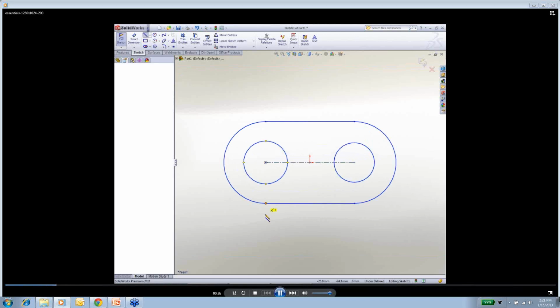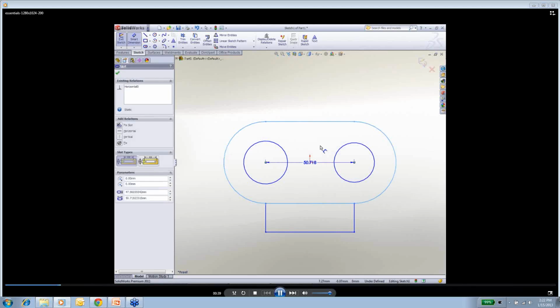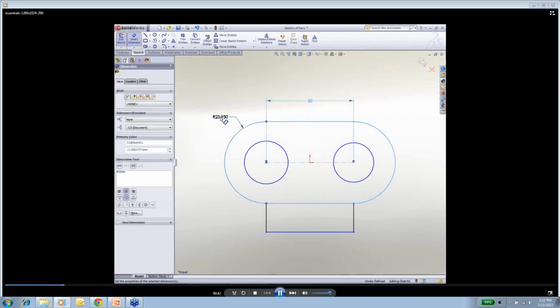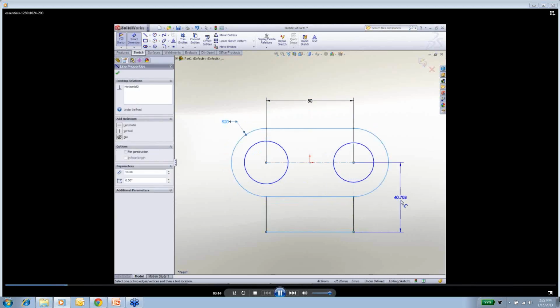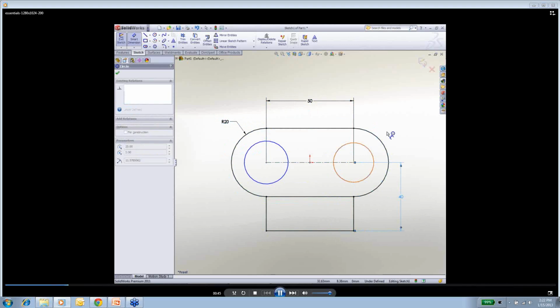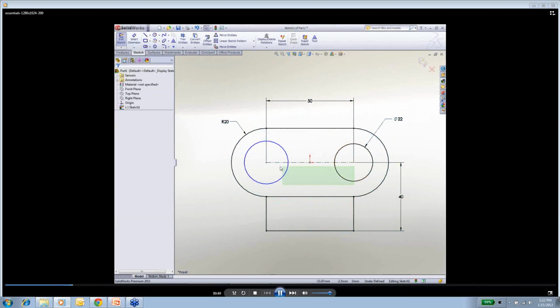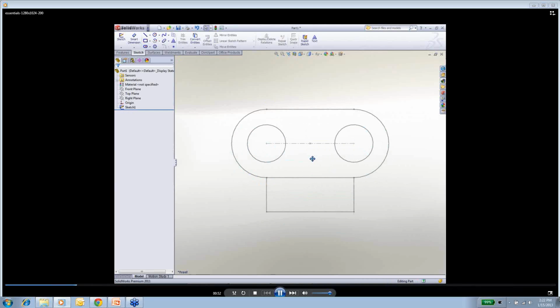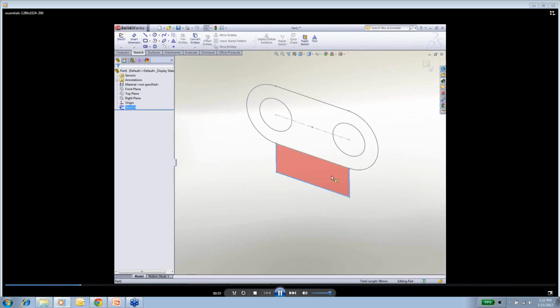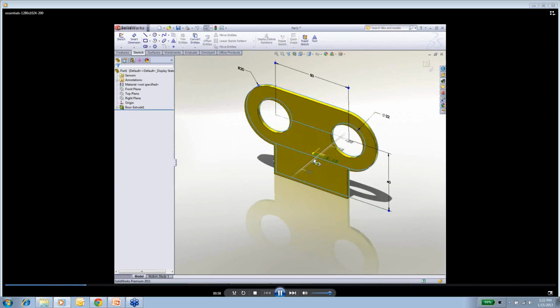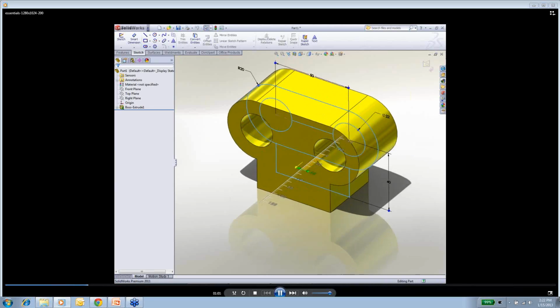So I'm just going to start a basic sketch. If you're using 2D modeling right now, it's like you're making a view in a 2D drawing, right? So I'm just going to make my 2D model. But what I can do is add intelligent dimensions. That means my dimensions actually drive my geometry. So when I make a change to any of these things, that section, that thing that I sketched, updates in scale. Now I can take that sketch and I can just add depth to it.